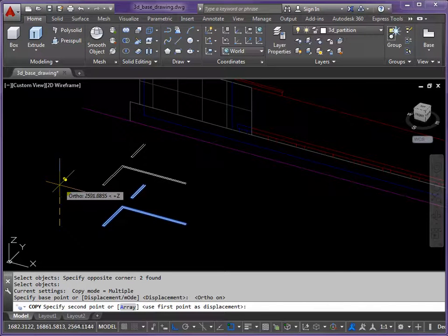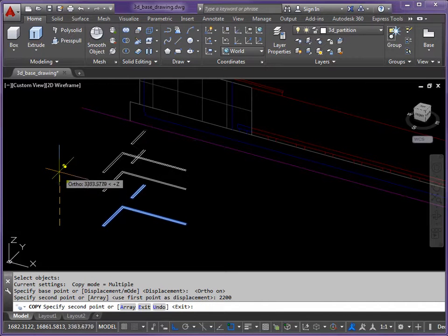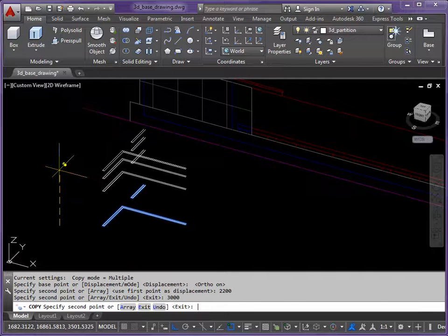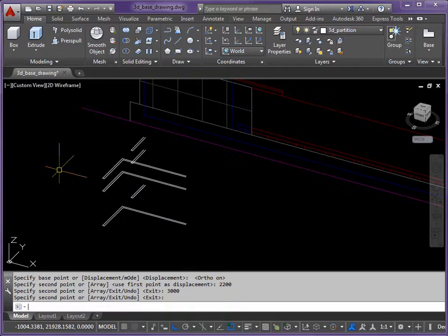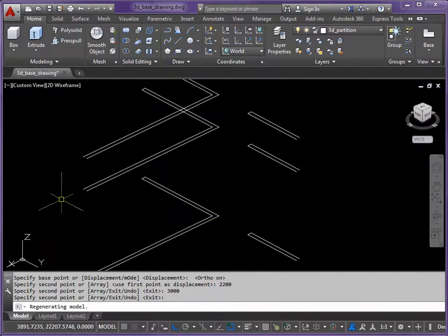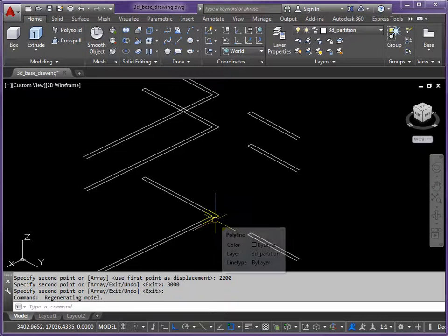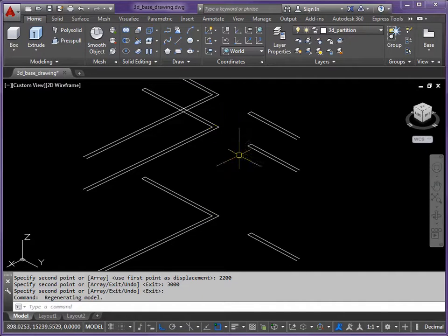Okay, so we've got +Z showing at the cursor, and we'll say that the door height is 2200, a bit more generous than a standard door, and then to the top of the walls would be 3000. Then press enter to finish. Now we need to identify another point across the doorways. So we're going to need a line from endpoint to perpendicular. Then we can copy that up to this point as well.